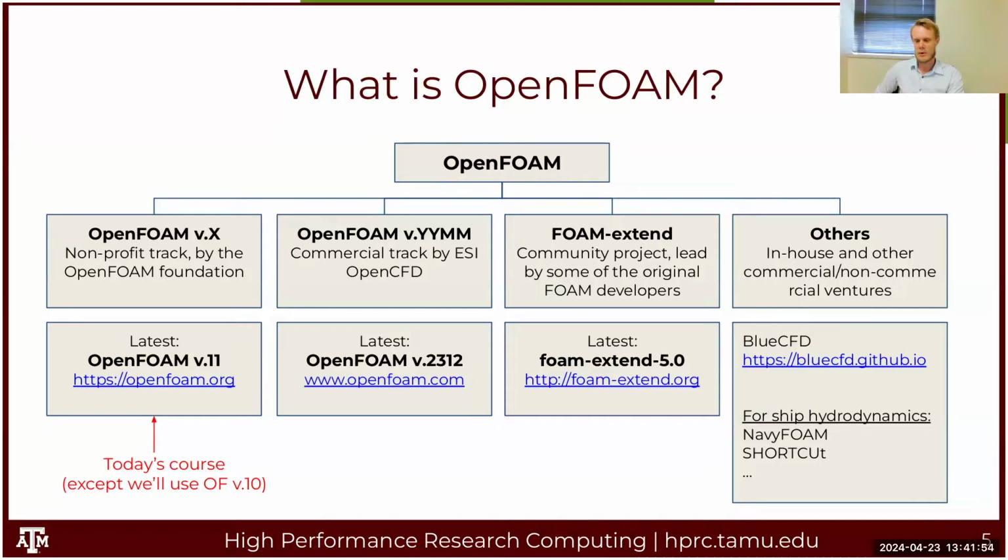One that I wanted to point to is one called Blue CFD, which is basically an emulator of a Unix environment for Windows. So that will run in Windows. So it's good if you're not sure if you want to take the plunge and install a new operating system to run OpenFOAM, you can test it out in Blue CFD, and it runs fairly well. I will say though that it will be slower than if you run it natively on a Unix machine.